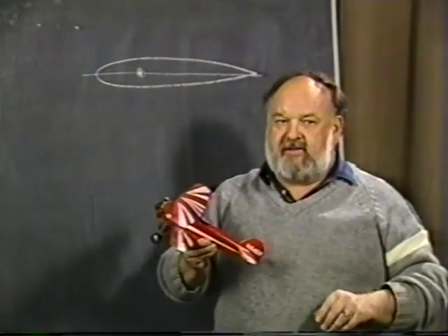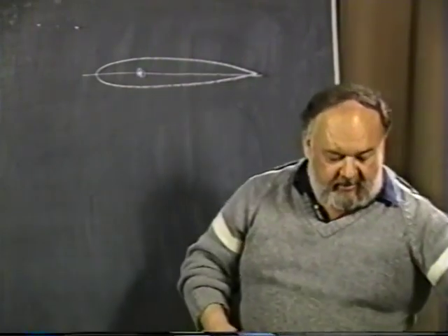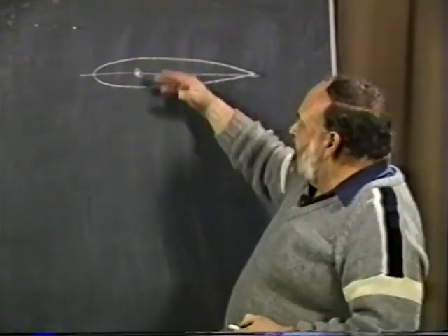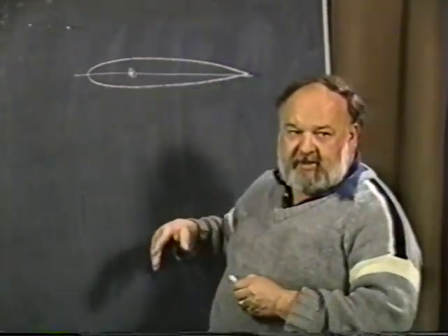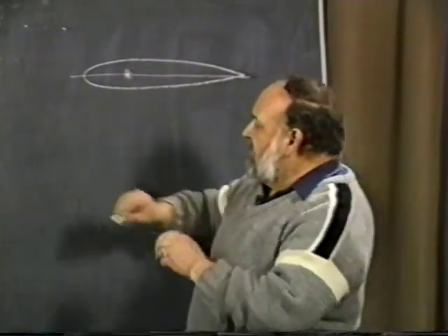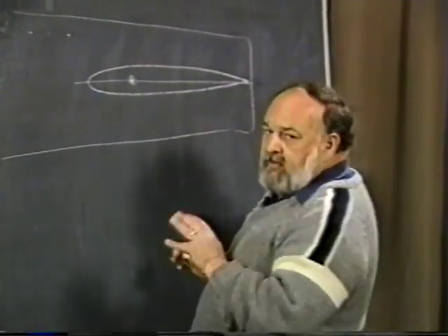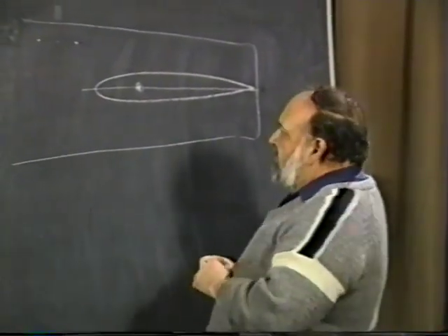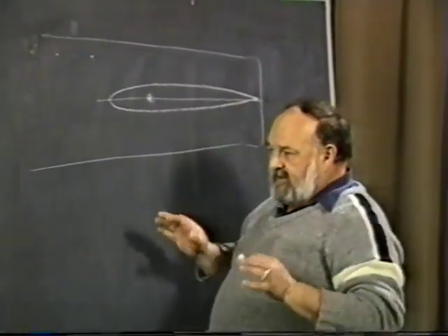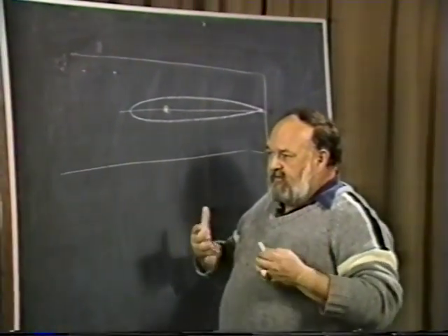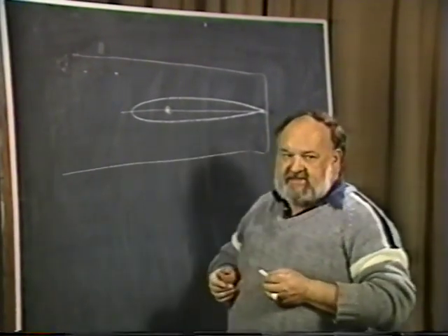But say you stay within the normal range of stability on the surface, the loads will go up or down depending upon the angle of attack, but the surface itself, relative to the fuselage, drawing this as the fuselage in here, will stay the same. So that part's real good. That means your airplane with your hands off is as if the tail's locked solid.